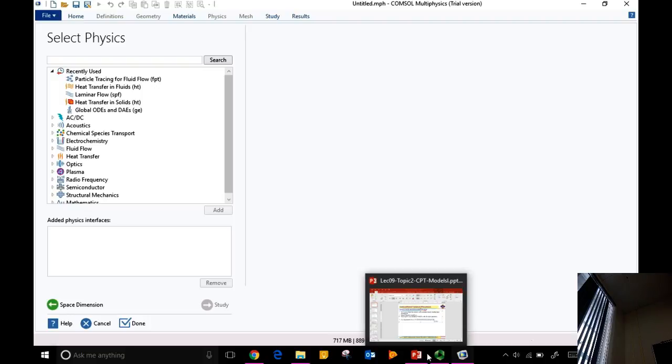Okay? And that spontaneously becomes unstable, and you get this 2D axisymmetric flow. If you keep increasing the rotational speed, this also becomes unstable. And then you will get a 3D transient flow towards turbulence. All of this will happen in the same geometry depending on the degree of forcing that you have, the Reynolds number or the Taylor number.